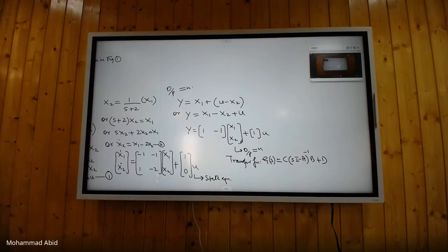जरा करके दो ये जल्दी. पहले (sI minus A) inverse obtain करो, then do this C (sI minus A) inverse of B and then add it to D, and then tell me what is the transfer function of the system.